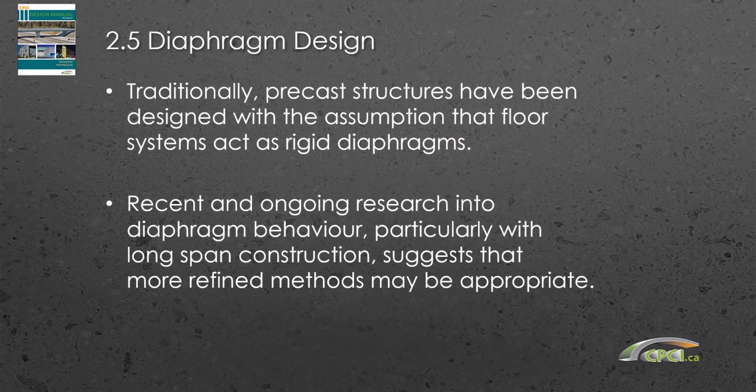Traditionally, precast structures have been designed assuming that the floor system acts as a rigid diaphragm, but recent and ongoing research into diaphragm behavior, particularly with longer spans, suggests that a more refined method may be appropriate for looking at your diaphragm design and the distribution of load to the lateral load resisting system elements.